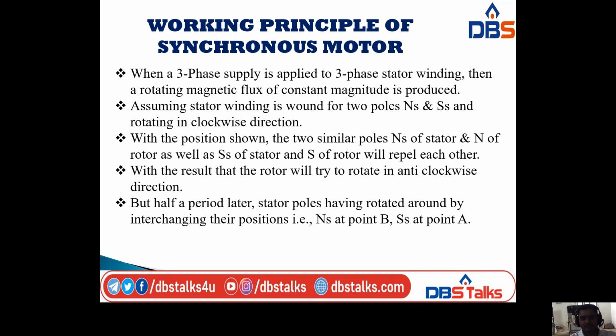Coming to the working principle of the synchronous motor, in the previous class I also discussed the magnetic locking concept. The same principle is used here. When a three-phase supply is applied to the three-phase stator winding, a rotating magnetic flux of constant magnitude is produced. I already said this in the previous class, in the construction details and in the production of the rotating magnetic field. Here the three-phase stator winding is connected to the three-phase supply, and it produces the rotating magnetic flux of constant magnitude.